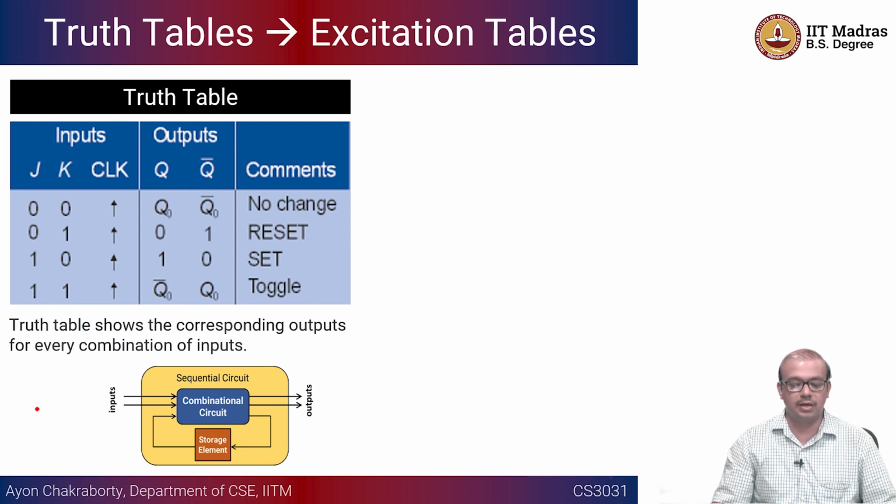Okay, so in case of our flip-flops, here also you can find out, let's say for a JK flip-flop, the inputs are J and K, and this is an edge triggered circuit, there is a clock, what should be the output? Given the current output, because it is always going to hold a state, right, there could be an initial state of the flip-flop that we are considering, that is going to be called Q0.